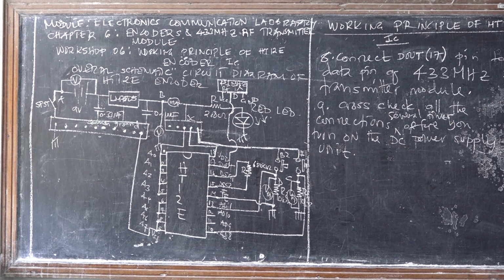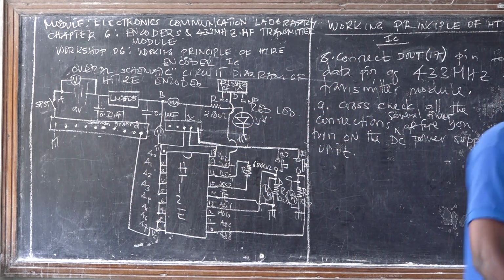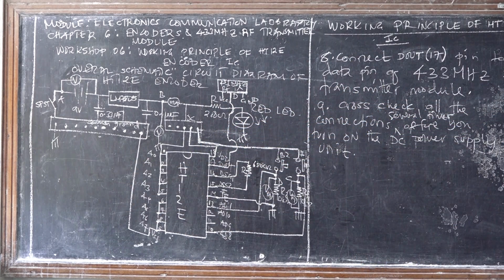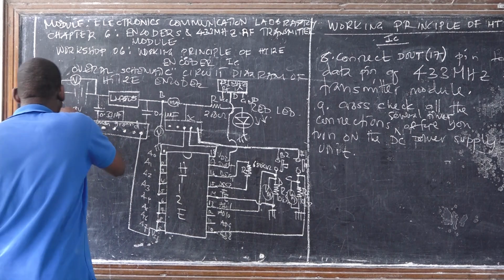We have switches in electronics; they just work like this one. This is an on-off switch. It's not an electromechanical switch, just an on-off switch to control power. Because if you don't have an on-off switch, while you are connecting, the power is flowing. Sometimes you make a mistake and then you damage the electronic components. Remember that this switch is not turned on until you go to step number 9.